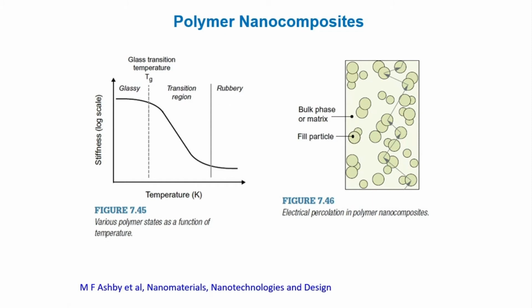The properties of nanocomposites rely on a range of variables, particularly the matrix materials, loading, even the degree of dispersion, size, shape obviously, and in addition the orientation of this second phase. So among the various nanocomposite types, the polymer-matrix composites have been the most widely studied, because you can have different kinds of variations possible in polymer-matrix composites.